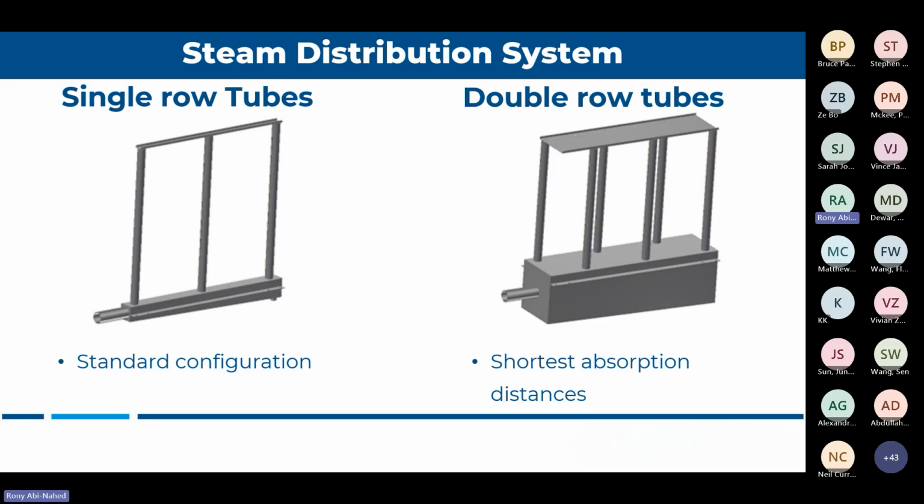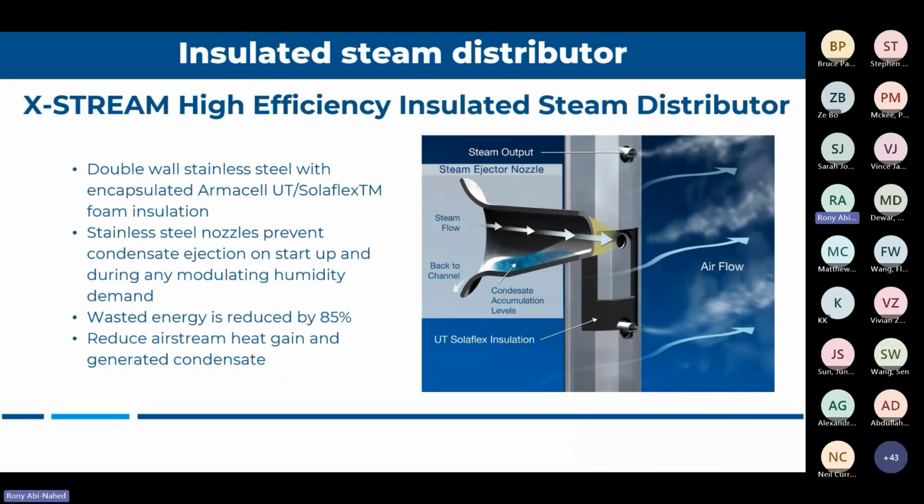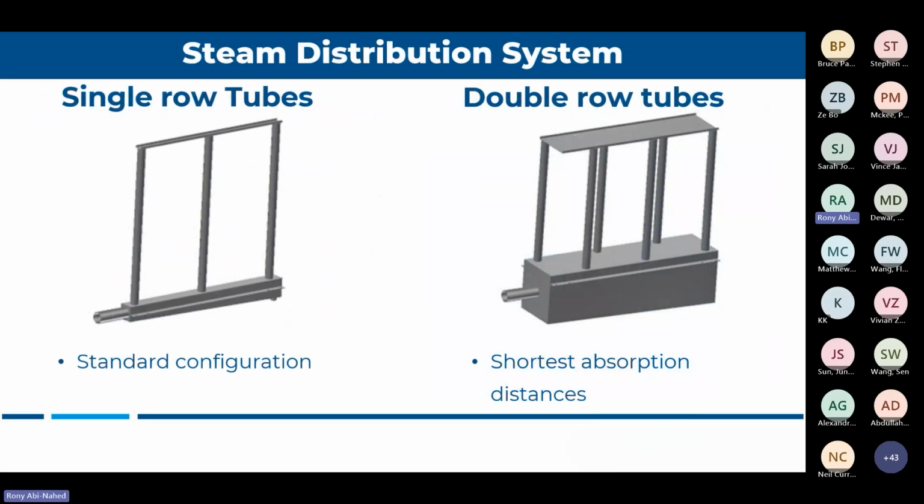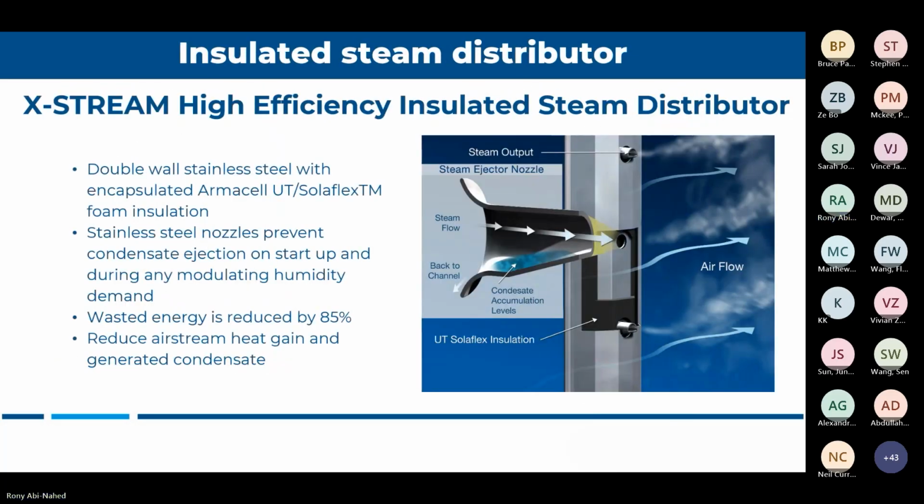Now, also when you're designing a job, you have the option to go with a standard grid or an insulated grid. So why do we insulate the grid? It's important to keep in mind insulation, that's where you will be saving tons of energy. If you remember when I was talking about the gas unit, I said you have the condensing one and the standard one, there's like a 4 or 5% efficiency difference. And that's not where you're going to save money. Where you're going to save money is really in insulating your grid.